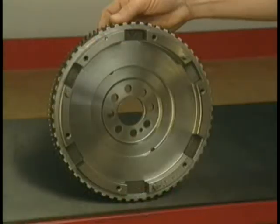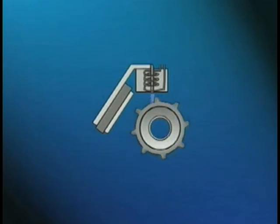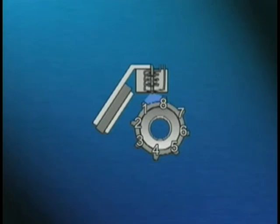The number of teeth on the crankshaft rotating wheel are equally spaced in terms of the degrees of crankshaft rotation. The number of teeth on the crankshaft rotating disc vary by the design of the system from 12 to 48. Most designs have one missing tooth that indicates the position of the number 1 cylinder at top dead center. Where the magnetic pulse generating sensors are mounted in the distributor, there is typically one tooth for each cylinder.